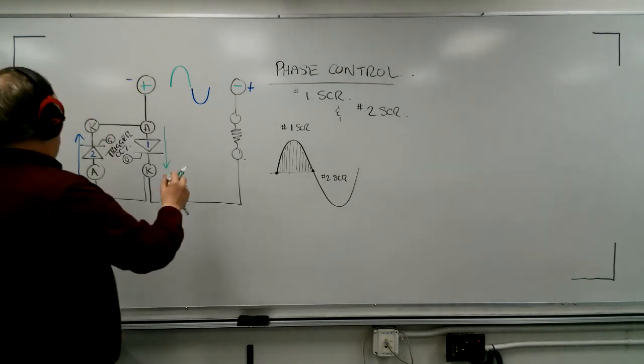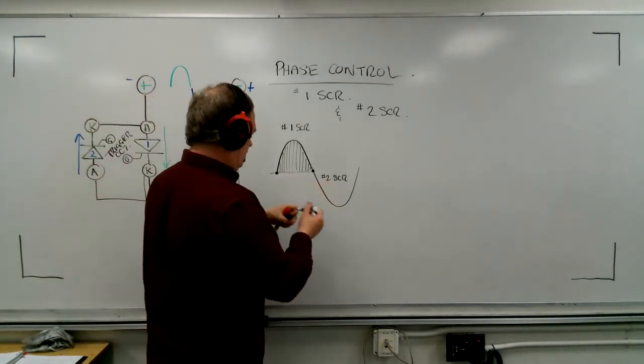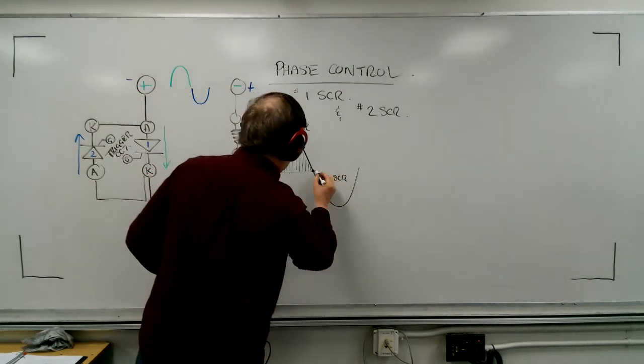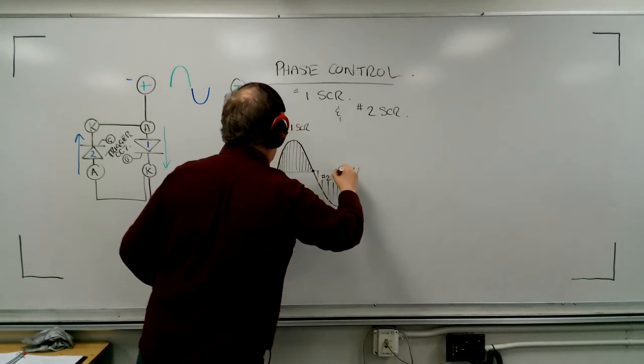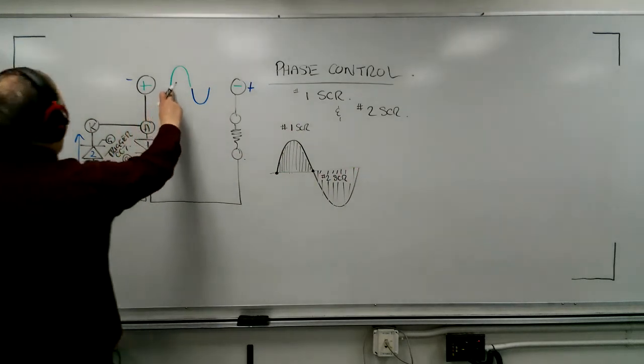So now SCR1 will handle this side and SCR2 will handle this side. And now we can conduct all the way through here. So now we're handling both alternations.